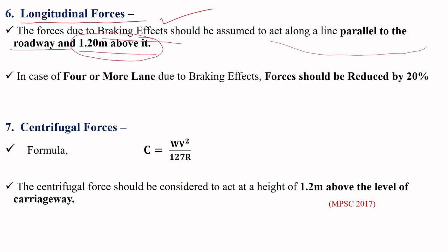So the forces due to braking effect should be assumed to act parallel to the roadway and 1.2 meter above it. That is the line of action of the force that is acted due to the braking effects.